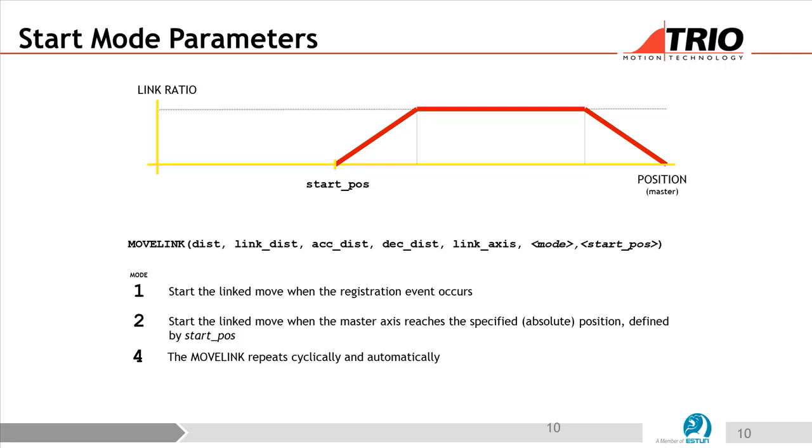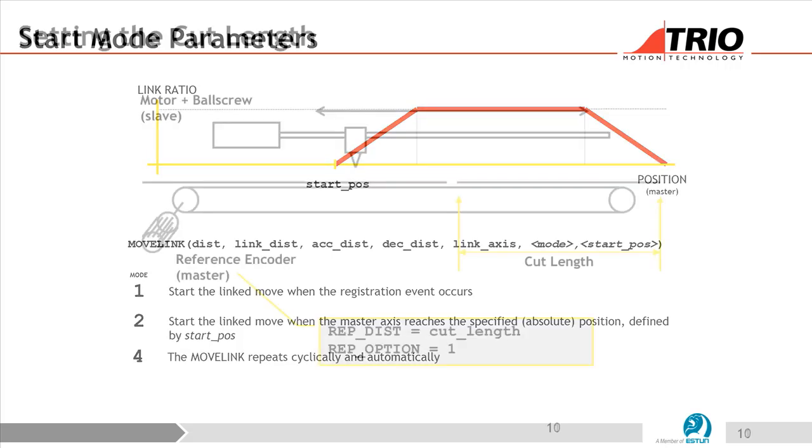And all of these motion commands that do link motion have the same options. So when we look at flex, link and cambox, you can do the same thing. There are more options that are not covered on here. There's another option that allows you to make an S profile instead of a trapezoidal one. So if you want an S ramp start, there's another option for that. It's all in the help file.